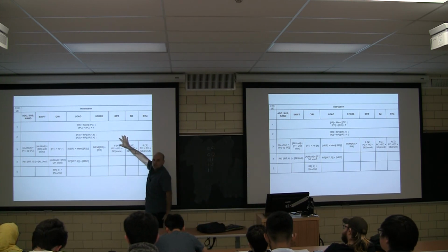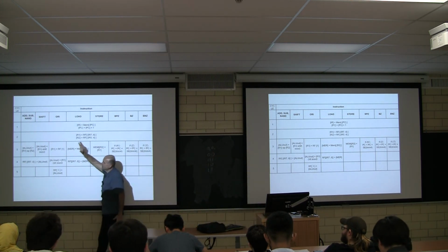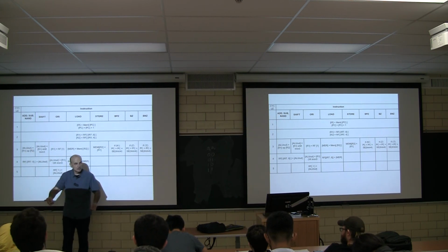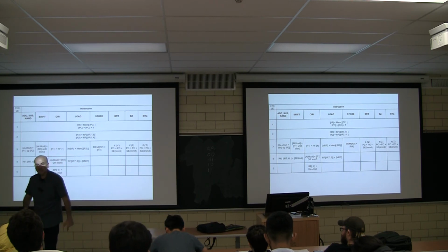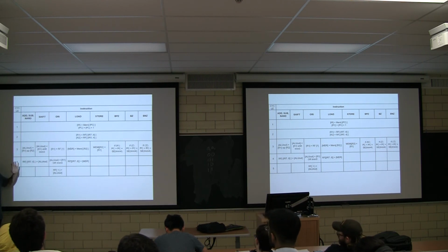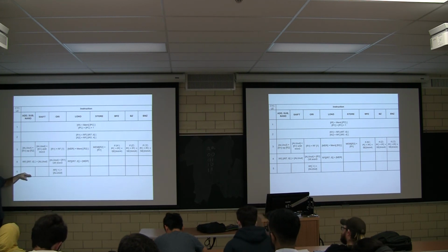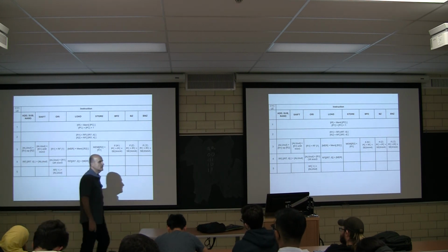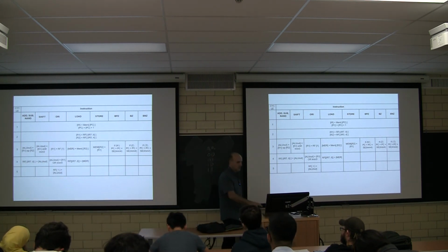So this is speculation, we're reading values. Let's go to the add. Next thing, now we're certain this is an add, subtract, whatever. If it's an add, we're going to do the calculation in the ALU. We're going to take 1 clock cycle to do that. We're going to put the result into a temporary register called ALU out, not visible to the programmer. And at the last cycle, we're going to write this back to the register file. Ta-da, done. The PC was changed in the first clock cycle, that's okay. We don't have to spend an extra cycle. Why? Because we designed the instruction set so we can do that. Fair enough? Let's look at the data path now.